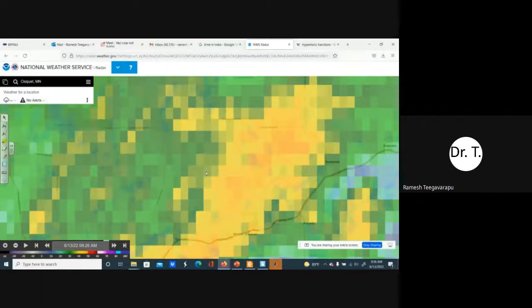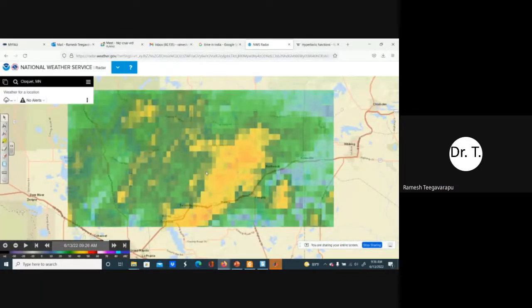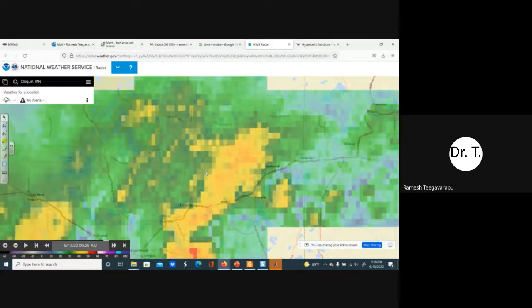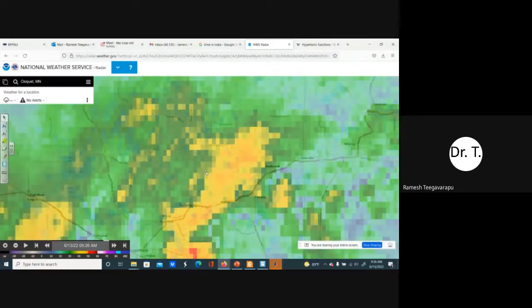That is a very important question. Yes, we have to go through a little bit of quality assurance and quality control of your rain gauge data. What is important is that you need to have reliable rain gauge data. Otherwise, bias corrections will be in error. Rain gauge data also might have some level of error, systematic as well as random. There can be anomalies and outliers.